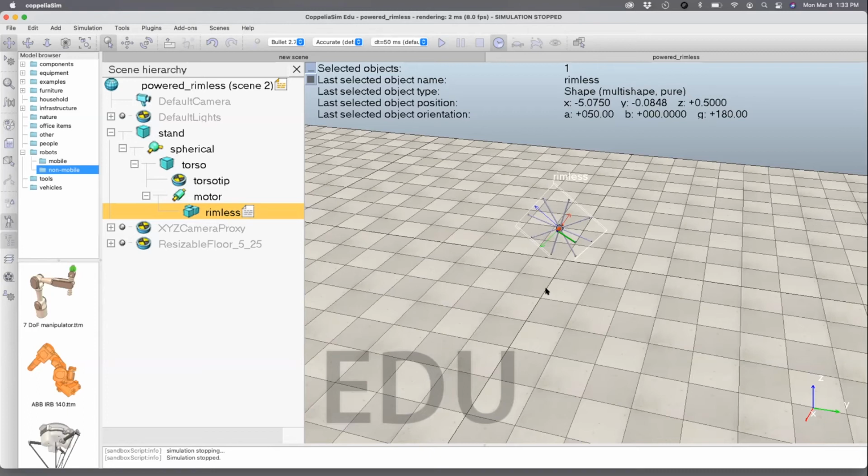It basically gives you positive angles if the torso is forward or backwards, which is a problem with cosine because it's an even function. The other method was to use the transformation matrices, which is a great idea but requires a little bit of math. Now I'm going to show you a method which is more accurate than the spherical, as accurate as the rotation matrix, but probably requires less computation than the rotation matrix.